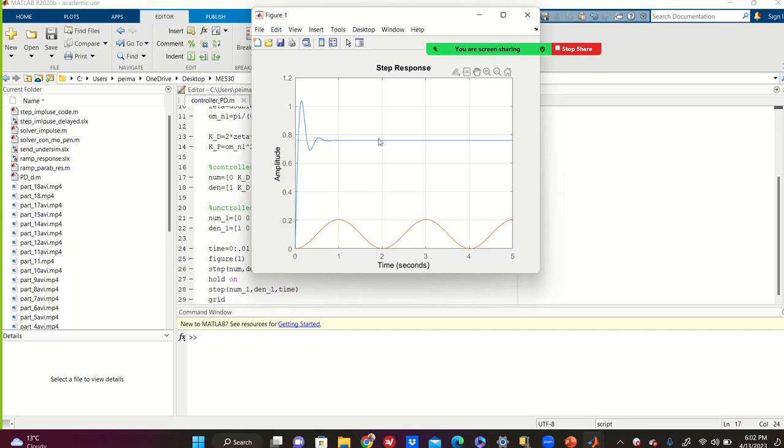It's 0.78. You see that? What I'm saying? Okay. Now your pendulum, based on the controller that you designed, going to 45 degree, or pi over 4, which is 0.78. This is the radian, that's right. And with the overshoot of almost 25 and the peak time of almost 0.2, almost. See what I'm saying? Yes.